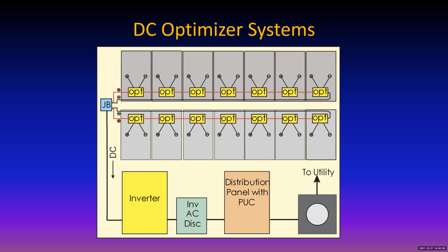But the modules themselves are basically self-limited, as you notice, even if you short them out, it doesn't damage them. The current that comes out of them is limited. So the modules are mostly fine, and if anything goes wrong with them, it's because they're being shaded. So I hope that is what you're asking. Rephrase it if I didn't do a reasonable job of addressing that.